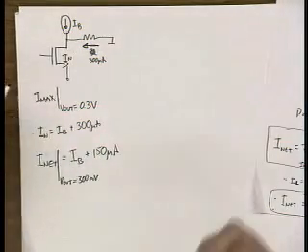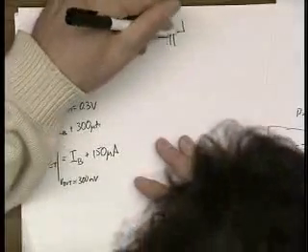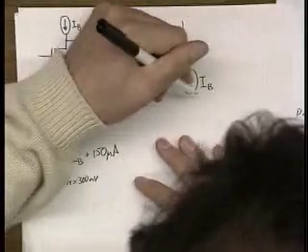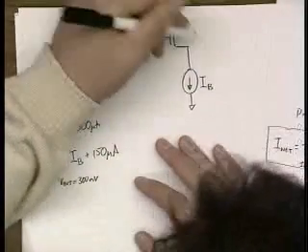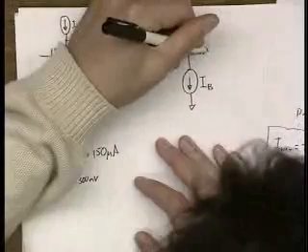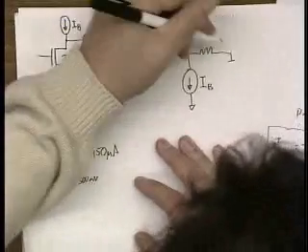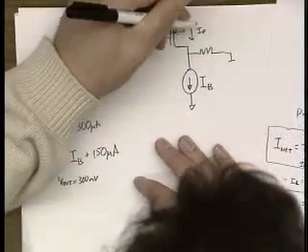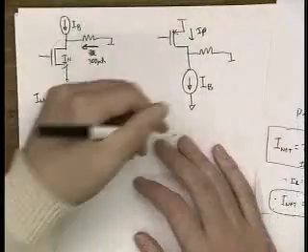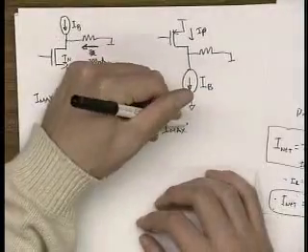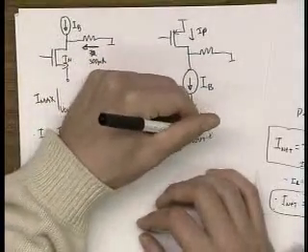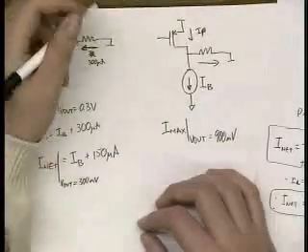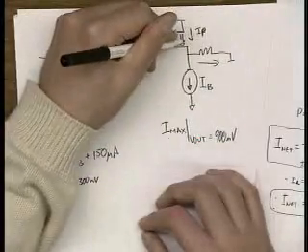However, if you do it the flip side, if you have a PMOS output stage, okay, then Imax is when V out equals 900 millivolts, because now you've got current flowing this way, and that means more current flows through this device.